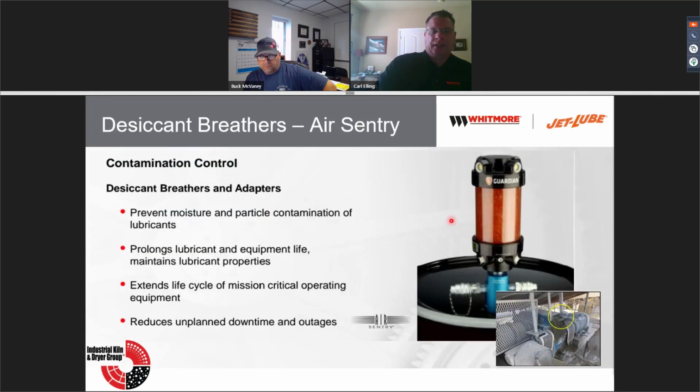Desiccant breathers. If you're not using them on gearboxes and hydraulic reservoirs, please consider them. These things will keep the moisture out as well as the particulates in the air that are floating around. And we all know, working in our industries, we've always got something floating around, and we've got high humidity areas. We manufacture Air Centric, and the Guardian series right here is probably the longest lasting one there.